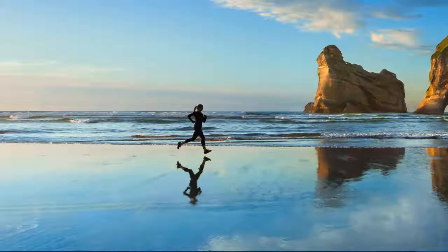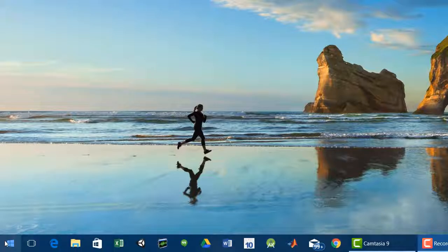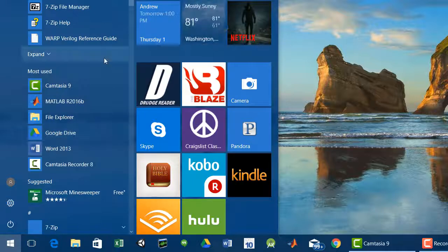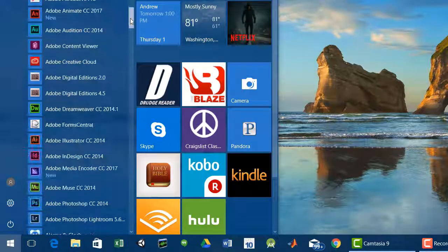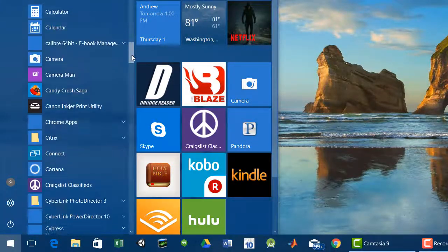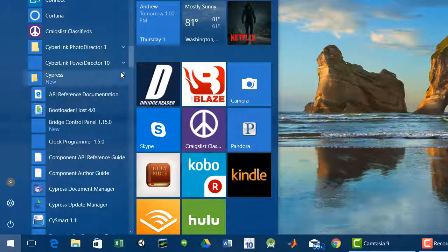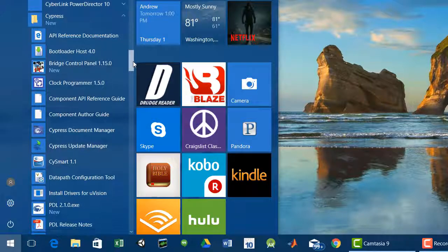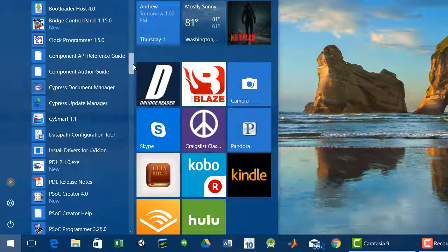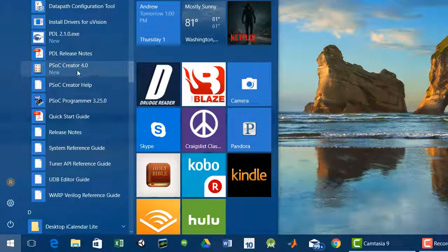In this video, I'm going to take you through writing your first PSoC code. Start by opening up PSoC Creator from the Start menu. Scroll down to find a folder called Cypress. Inside that folder, find the item called PSoC Creator.